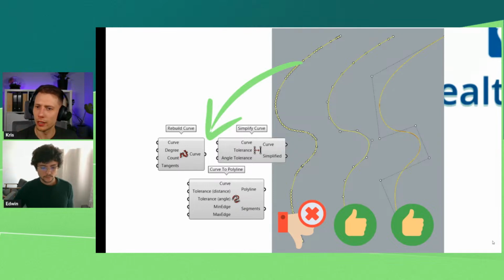If you are really into precision, for example millimeter precision, maybe you have to use more advanced components, and rebuilding the geometry of your curve can be more difficult. But if you don't care about millimeter tolerances, you can go with rebuild curve, simplify curve, or even change a really complex curve with a huge polynomial expression to a polyline.